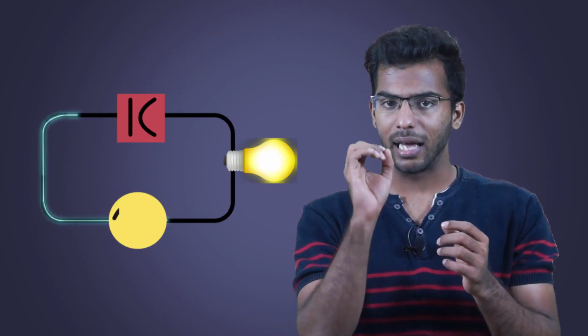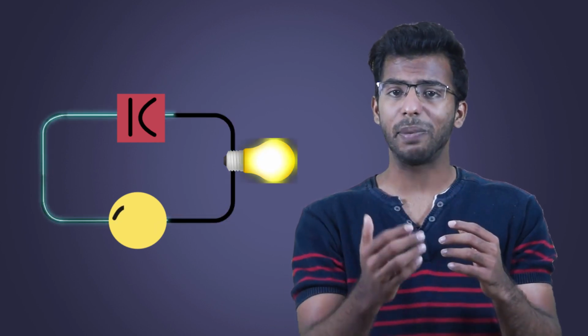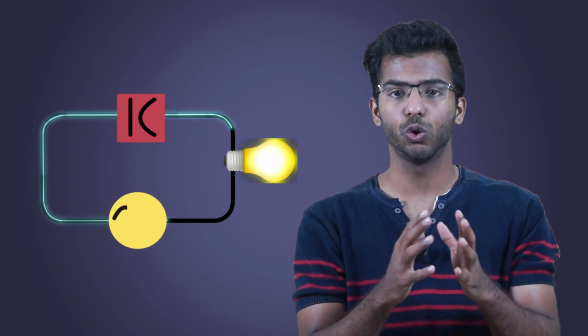If we apply an alternating current or AC supply, the capacitor will alternately charge and discharge at a rate determined by the frequency of the supply. Then the capacitance in AC circuits varies with the frequency as the capacitor is being constantly charged and discharged. We know that the flow of electrons onto the plates of a capacitor is directly proportional to the rate of change of the voltage across those plates.